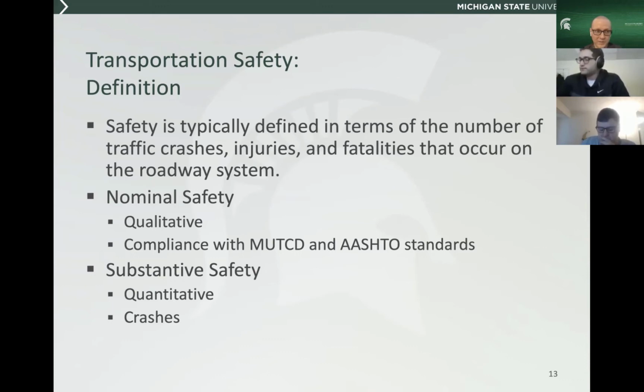And so one case, for example, you probably got into the controlling criteria in either highway design or advanced highway design. Are you guys familiar with the AASHTO 10 controlling criteria for geometric design? It used to be 13 controlling criteria. So these are basically minimum standards that have to be met.